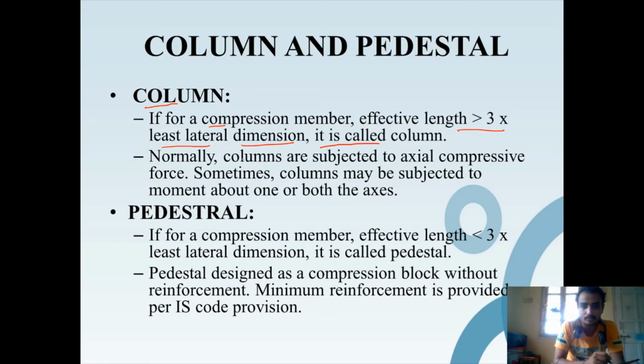Normally columns are subjected to axial compressive force, meaning only a compression force, but sometimes a column may be subjected to moment about one or both axes. Sometimes we have a moment on the column, but regularly we have only compression.